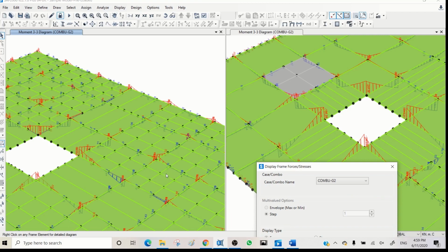So just bear in mind, anyway, this is a two-way slab, so matching the stiffness and displacement is important. When a slab reaches a certain displacement that mobilizes the stiffness of the slab, it transfers load automatically to the stiffer supports. So you just need to be really mindful of how you are using those elements, and whether you are accurate enough in transferring load or not. Currently you can see these areas look okay, but in some other areas you may not see too much load transferring.